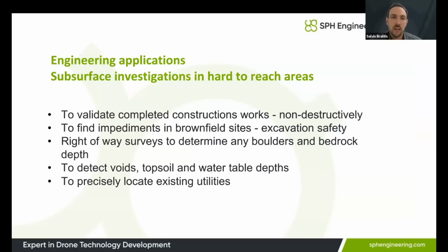Some of the samples and use cases that we've seen in the past are people using drone-based GPR to non-destructively validate the completed construction works. For instance, we had a case in the Middle East region where a contractor built a retaining wall, and for quality control reasons, they wanted to determine whether the actual wall was built to spec.